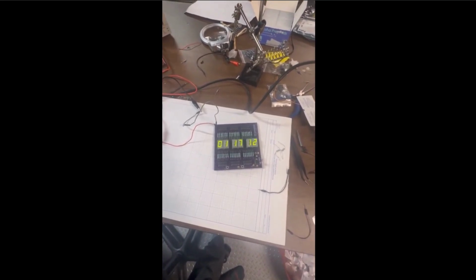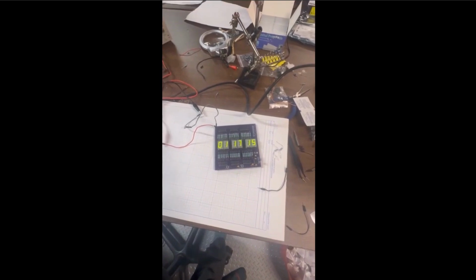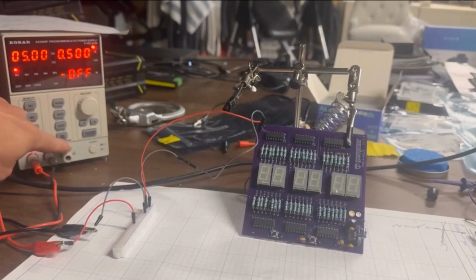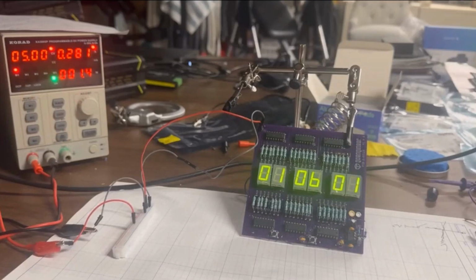So now I'll go ahead and test the switches. So one of 2 things could have been going on with my switches. The first is both of them are connected to the output of my AND gate, and I found out the AND gate latches the voltage at either 0 or 5 volts. The other thing that could have happened is I had a voltage divider going on with my output of my switch.